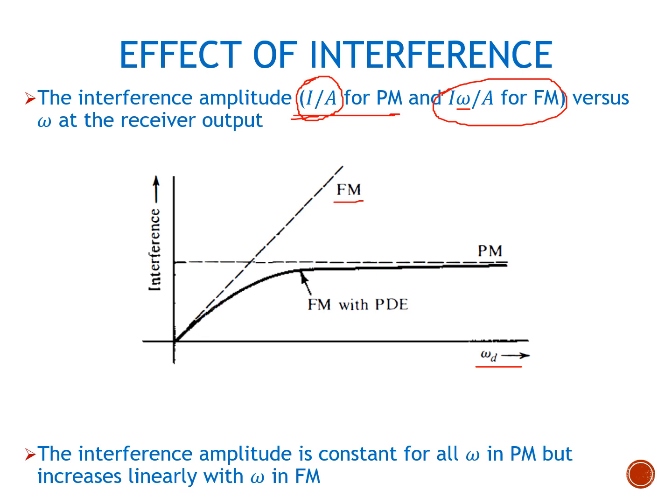Here we can see from this plot an interesting phenomenon: for the lower frequencies, the interference in the FM signal is low, and for higher frequencies the interference in the PM signal is low. So let's design a circuit. What pre-emphasis and de-emphasis do is allow us to design a circuit that uses FM behavior in the low frequency region and PM behavior in the high frequency region.